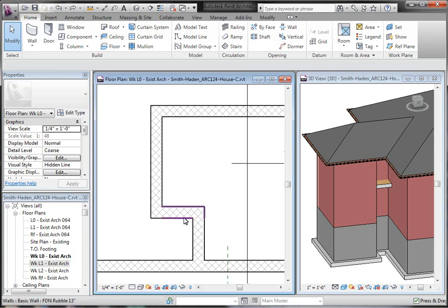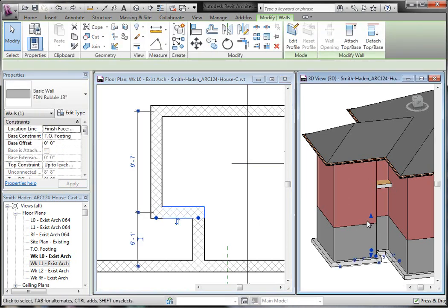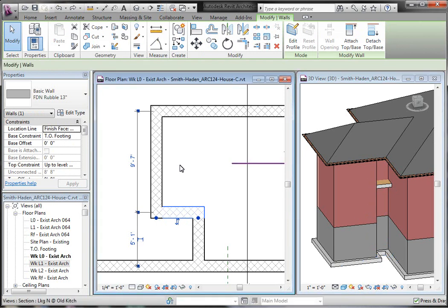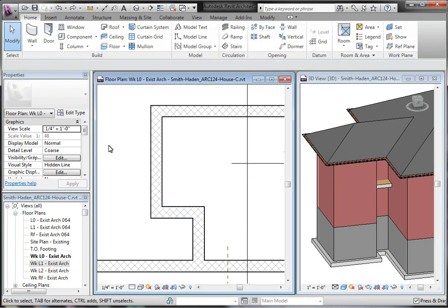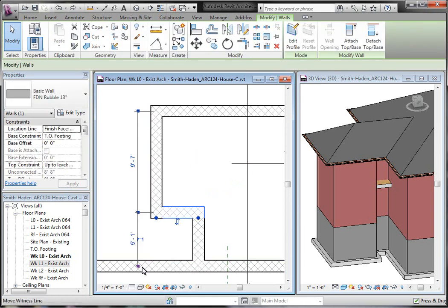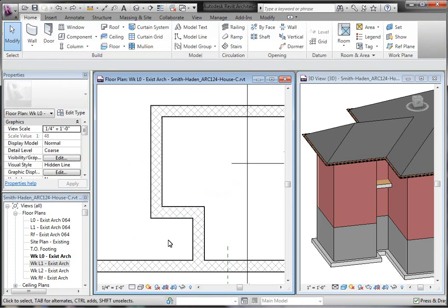But the tricky part is moving this basement wall so that it creates a notch down at the basement with an overhang up at the first floor. Believe it or not, this is the quirky little addition that was on a house that I used for the basis of this assignment. Okay, so the first method would be to select the wall and drag the endpoints of the temporary dimension, using tab.